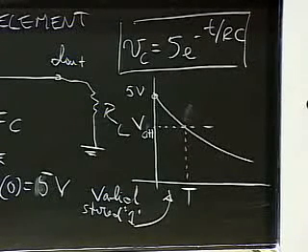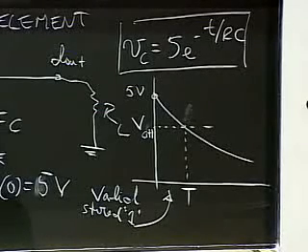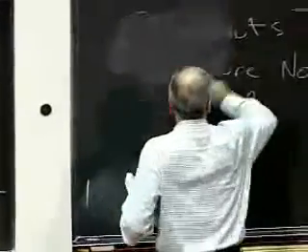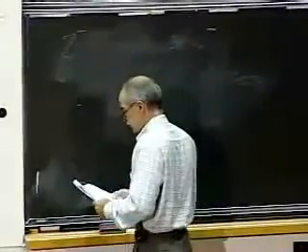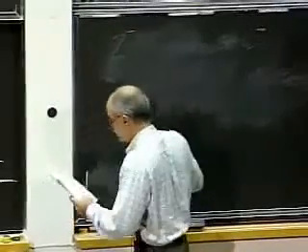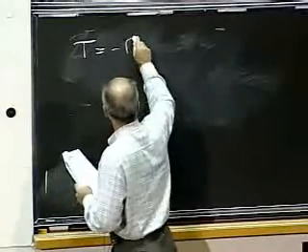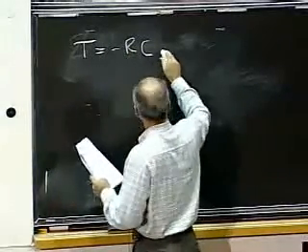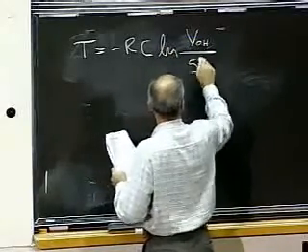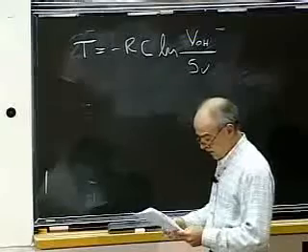Okay, so it is not a case in which the capacitor can hold charge forever. In fact, we can solve for T in this particular case. It's in your notes. Nothing really very profound. T is equal to minus RC log VOH over 5 volts. Okay, so this is basically what the response is going to be.